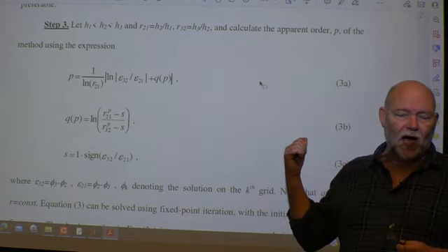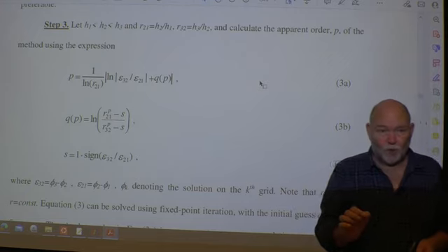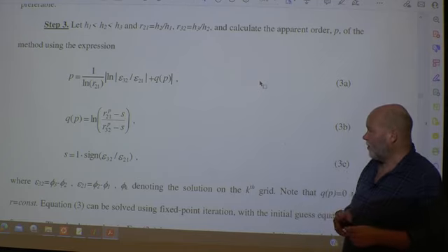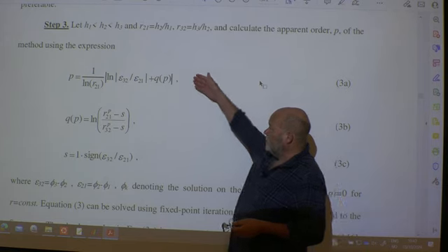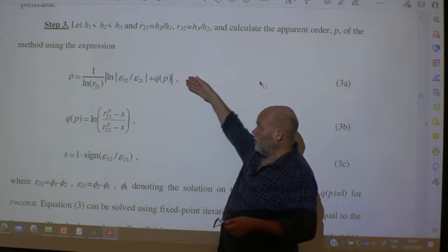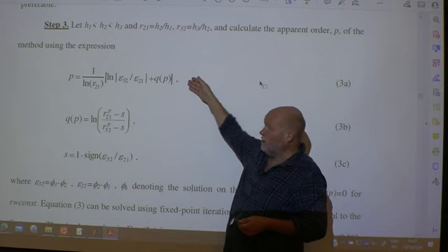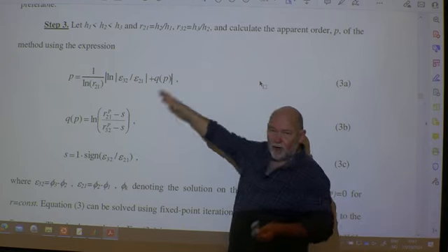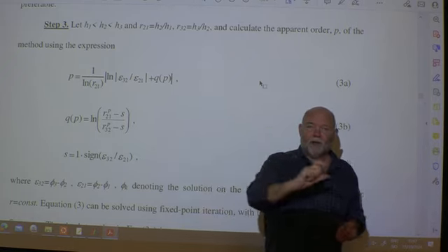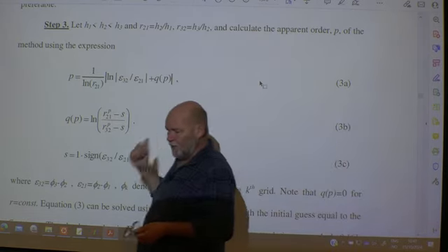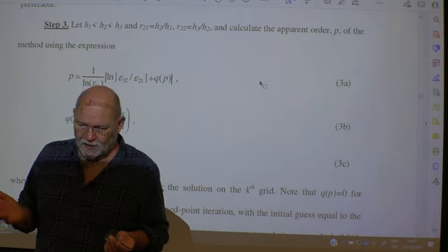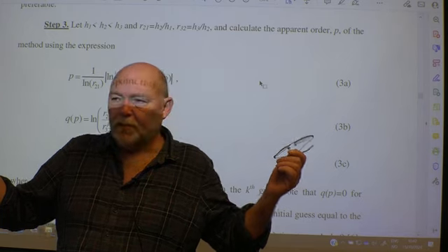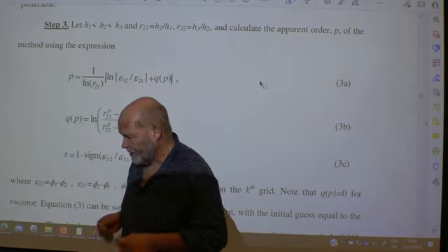So you don't have to evaluate this one for every probe, for every single time step. That will be a tremendous amount of work. So you can create one p average if you like, or you can have p 1 to 8 calculated after, say, 2 seconds, but you use that one for the entire time history to create the error bars. Remember, this one should reflect how good is your mesh. Hence, it should be time independent. That's the point.